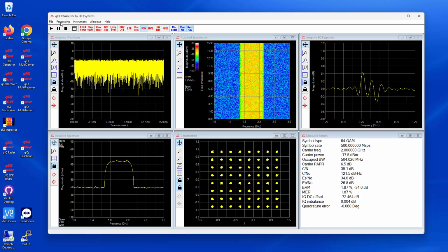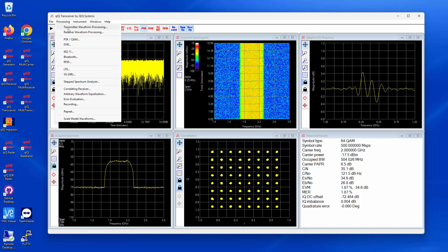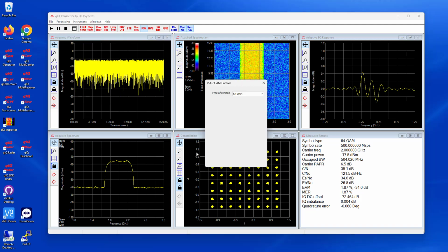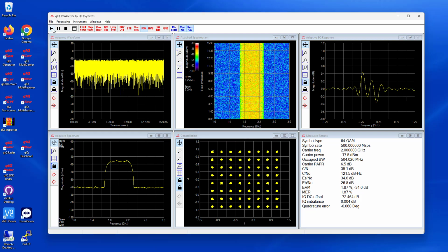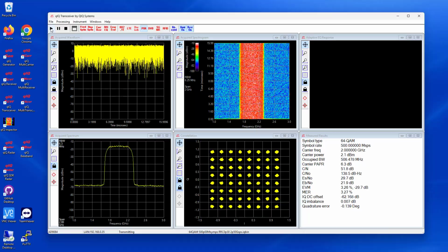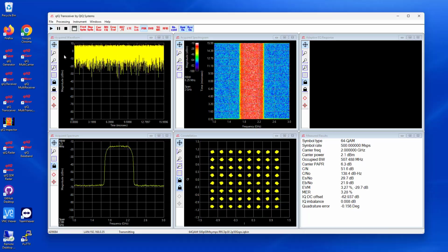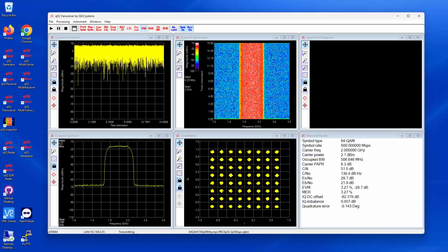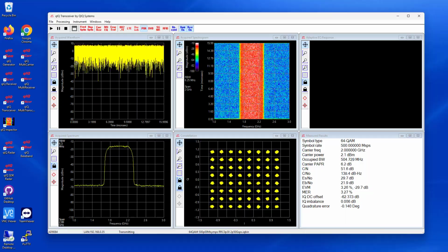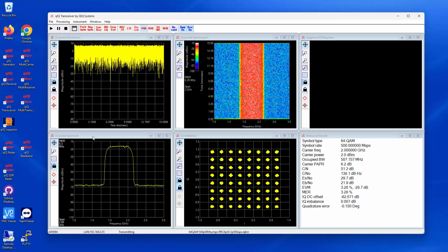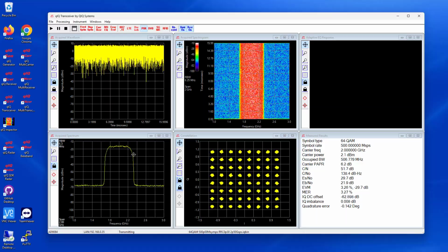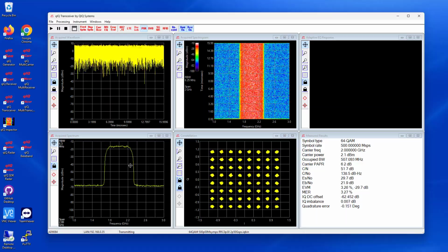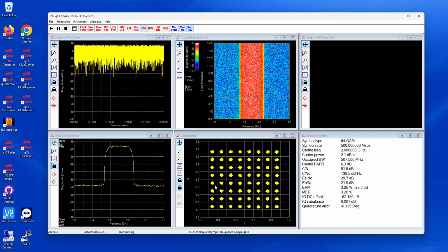We'll go in here and we will turn off the adaptive equalization for the moment, and we'll just use an amplified signal coming from the DAC output running through an Analog Devices AD9100 amplifier, and you can immediately see that the signal level is better in this case.